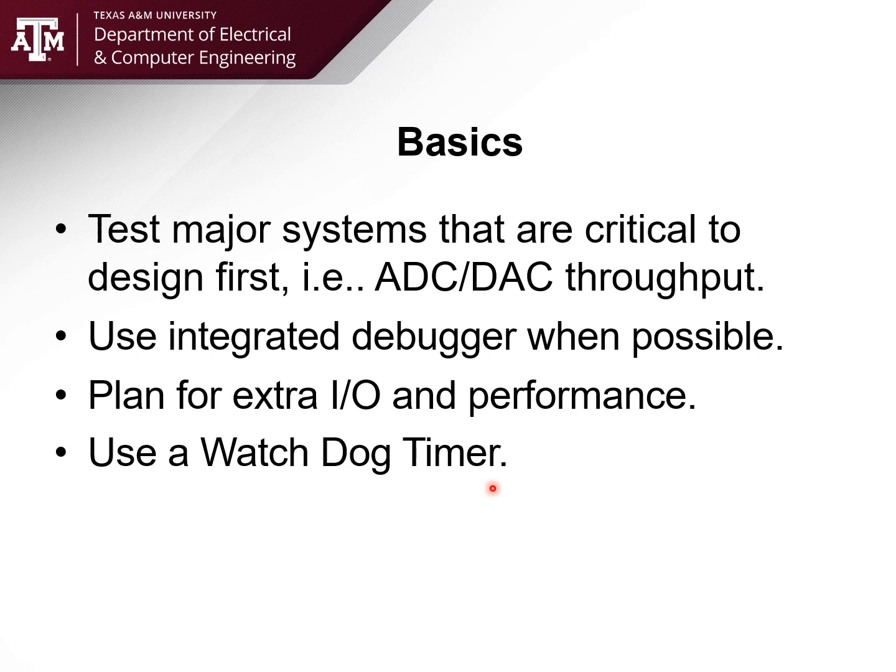you didn't get some information correctly, the communication locked up, lightning was nearby and actually caused the processor to jump in its program counter, and it's in the wrong place, in other words, it just completely loses it. So what you want to do is make sure that you have this device called a watchdog timer. And what you do is you pet the dog, you reset the watchdog periodically inside your program.